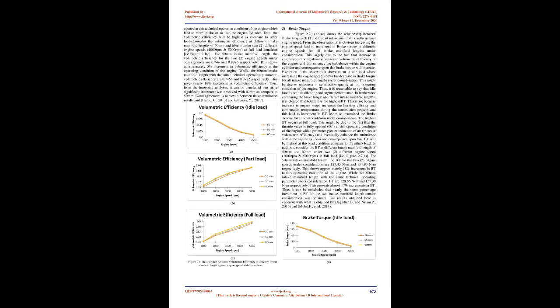The simulation was conducted with a 4 cylinder engine at different intake manifold lengths such as 50 mm, 55 mm, and 60 mm, with different load conditions, which are idle load, 10° CA, part load, 45° CA, and full load, 90° CA, and 30° BTDC representing the maximum brake torque spark timing, MBT timing, at different engine speeds ranging from 1000 to 5000 rpm. A stoichiometric mixture was adopted as the combustion strategy for the simulation.